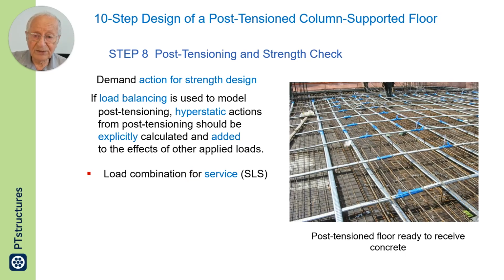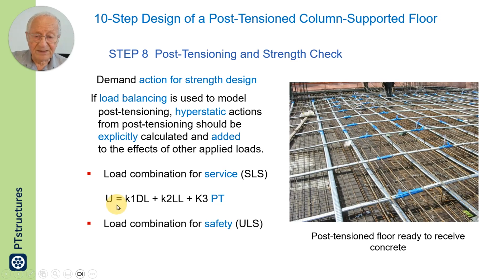The load combination for service is this: dead load, live load, and post-tensioning. But for safety, the dead load and live load moments are the same. The coefficients change. Here's 1, here's 1.2.